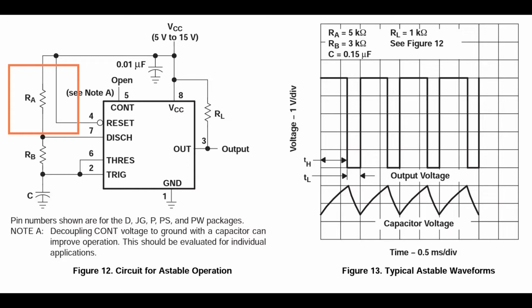So you see on the left here this resistor RA. And if you go down, you see the resistor RB, and then you see this capacitor just before ground, which is symbol C. These three very much determine how this thing behaves. Now, to say a general word, you put a random input voltage at the input, which is here VCC marked. And you see it can be from anything from 5 volt to 15 volt.